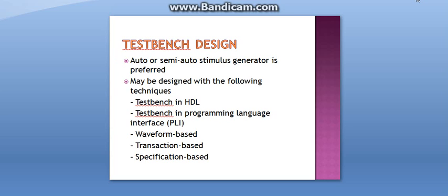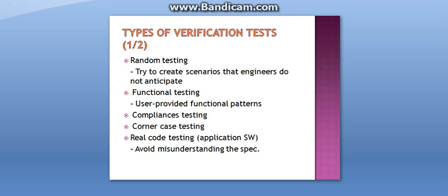In testbench design, an auto or semi-automatic stimulus generator is preferred. In that, automatic response checking is highly recommended. You may design a testbench with different techniques, that is testbench in HDL, testbench in a programming language and interface. Design with waveform based, design with transaction based, design with specification based. Types of verification tests are random testing, functional testing, compliance testing, corner case testing, real code testing, and regression testing.